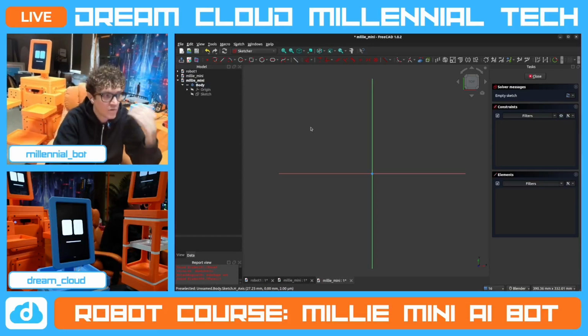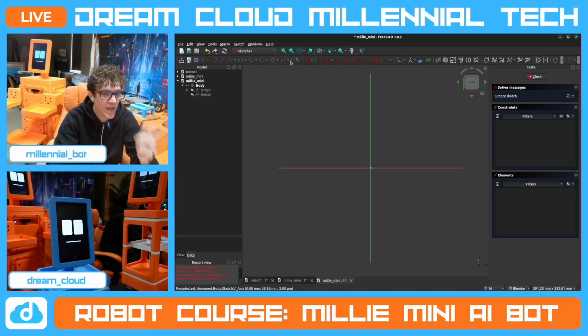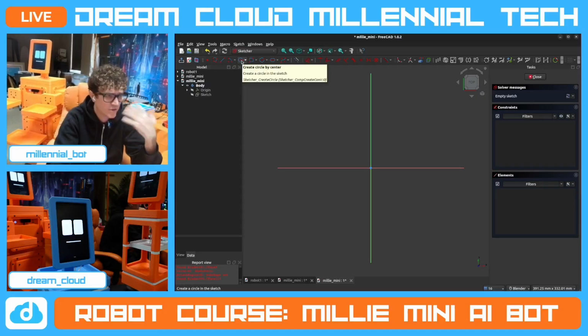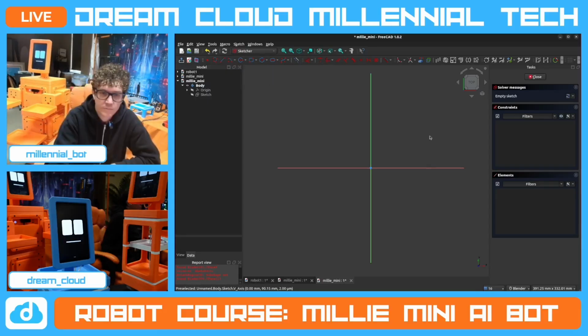So what if we wanted to draw lines that were guidelines? What if we wanted to draw reference lines that we could use to create a grid, and then on that grid we could make holes, but we don't want the grid to be shown? Well, that would be this one, which is changed to blue. Now we have all these blue lines that we can create grids with. We can create center points, reference points, and reference circles if we want to put a bunch of points on a circle or on a square or any other shape, or at the midpoint of a line.